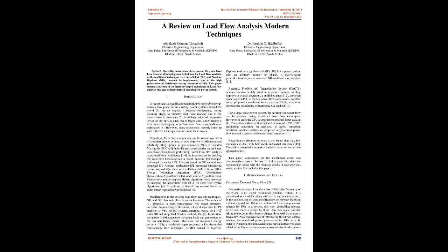For a power system with an arbitrary number of phases, a matrix-based generalization for power mismatch NR load flow was proposed. Recently, flexible AC transmission system, FACTS, devices became widely used in a power system, as they improve its overall operation. A published paper proposed modeling UPFC in the NR power flow calculations. Another author proposed a nonlinear iterative solver, NLIS, which can increase the practicality of traditional GS method.